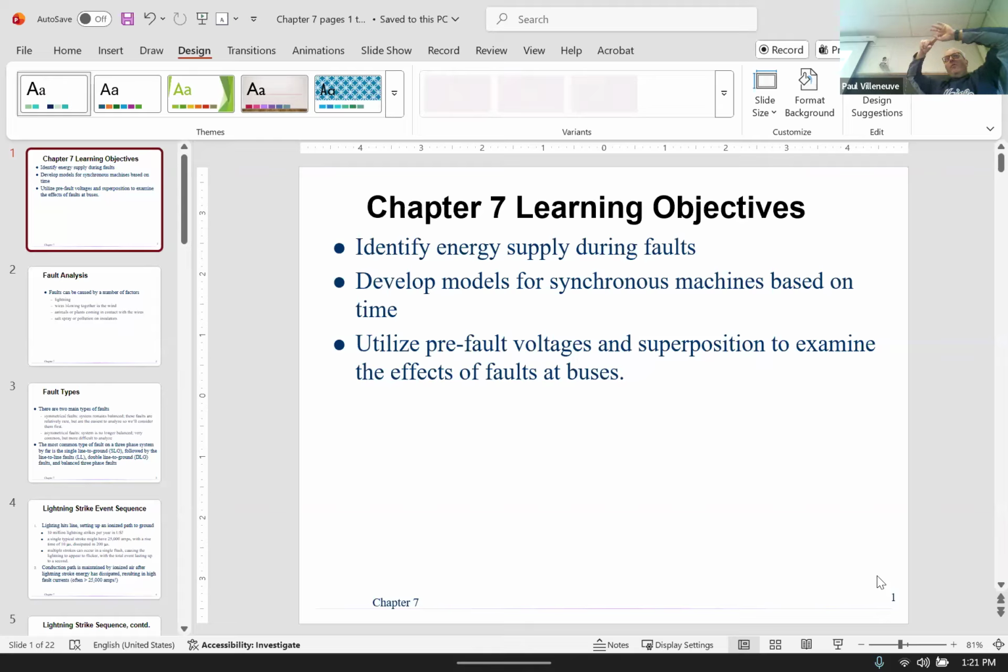So when the fuse is running at too high a current, it generates a temperature. What happens to sand when it gets hot? Turns to glass. So now you've got glass that's leaning on the stuff that's melting, and it makes it impossible for current to conduct. And the glass forms very quickly, like I said, less than a quarter of a cycle, which is less than 4.5 milliseconds. And so the fault current gets shunted very quickly. So the fastest devices to isolate current today still is a quarter cycle, and those are current limiting fuses.